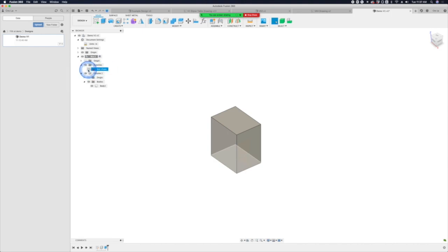If I want to, I can also use this, and it automatically makes that sketch disappear. The little eye on the left will make things visible or invisible, so let's make that visible again. I can hide this body, or I can do the same thing by hiding this component. It makes more sense when you have a lot of geometry for a more complex shape.